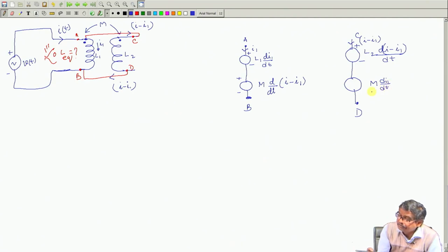Now, the next thing is whether this is plus and this is minus, or the other way around. Who tells me that? This dot convention. Through the dot, current is entering in coil AB, and that current is causing an induced voltage here, where the dot is known. So, the upper should be plus, lower should be minus. And then the circuit is, these two are connected in parallel.